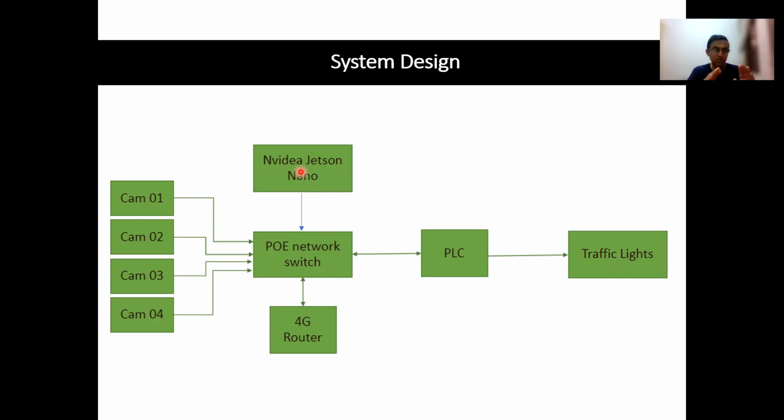It will not stick to the static timing at this moment of time. It will adjust it slightly. Now, when you do the adjustment, it's better if you keep the same cycle time initially. So it may be a 150 second cycle time, divided into four phases if it is a four-phase system.